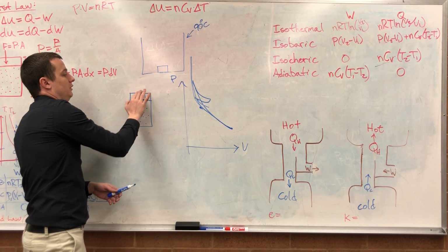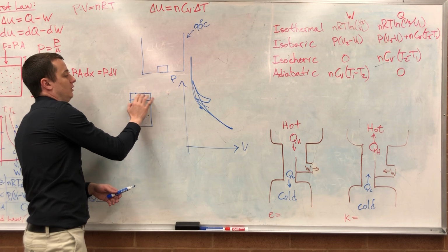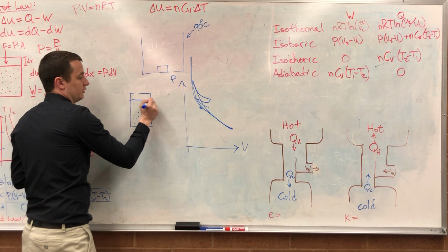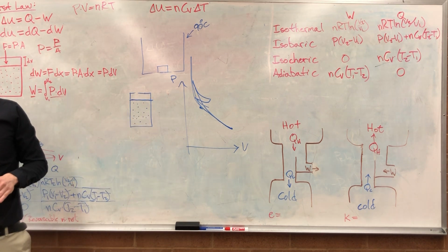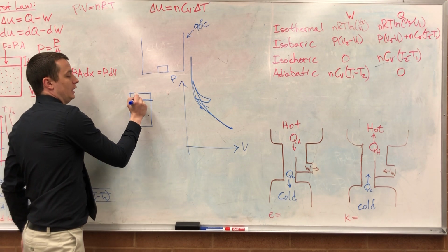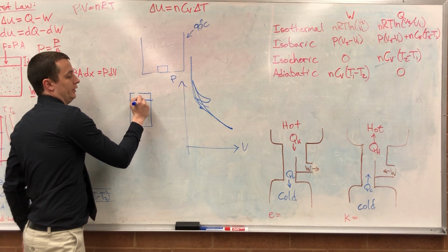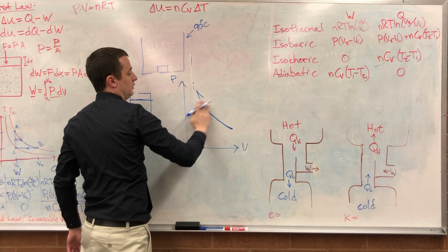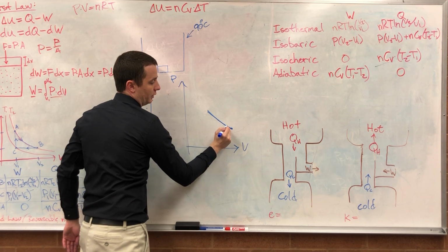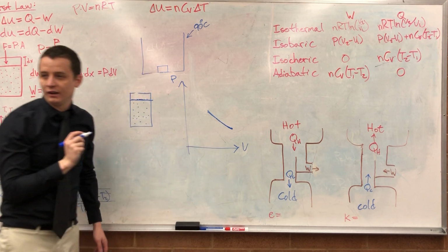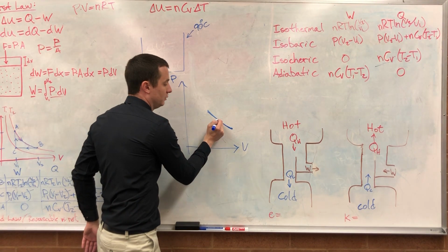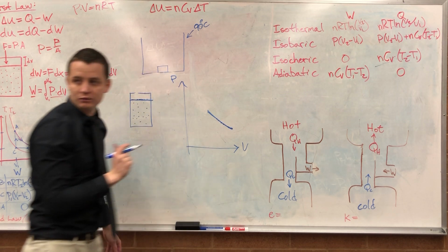Here's a similar one that we call an almost reversible process. It's really close. One that we can reverse would be, I've got this piston now, and instead of dropping a rock on it to compress it, I start dropping grains of sand on top of here. One little grain of sand at a time, and it's slowly going to inch this way, more and more. Now if I want to run it backwards, I just start removing one little grain of sand at a time, and that's going to start running it backwards.